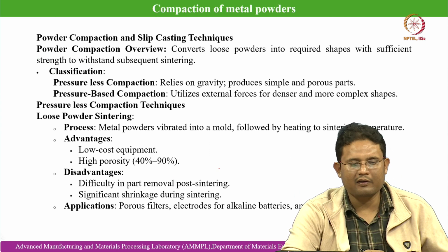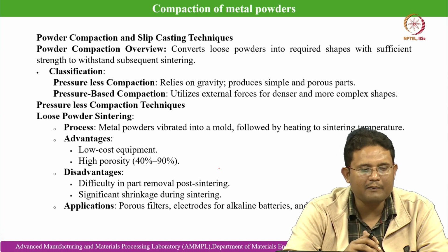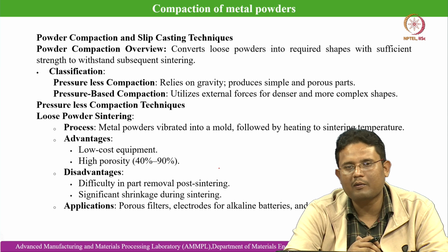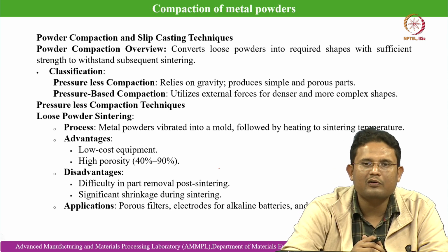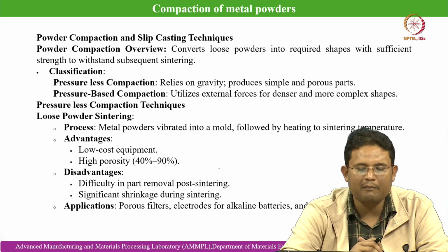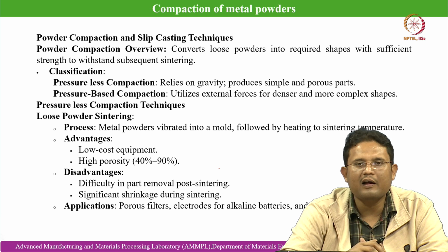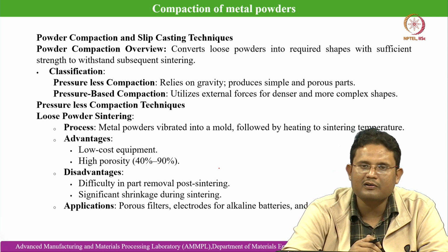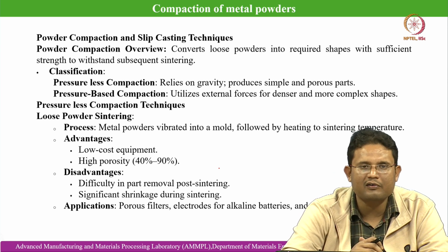So these are basically the powder compaction and slip casting techniques. The powder compaction overview is already given to you, which converts loose powders into required shapes with sufficient strength to withstand subsequent sintering. Classification can be done as pressureless compaction and also as pressure based compaction. Pressureless compaction examples are loose powder sintering.